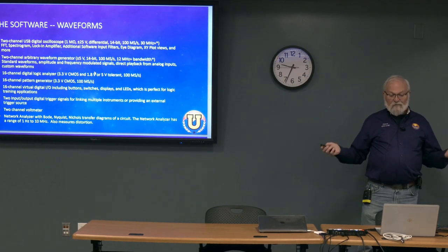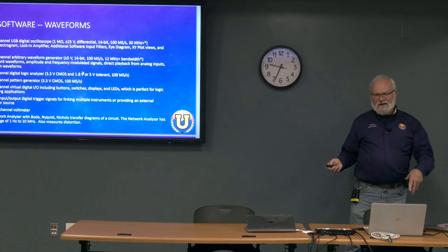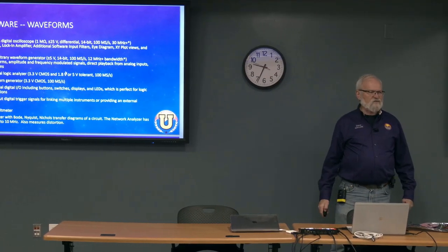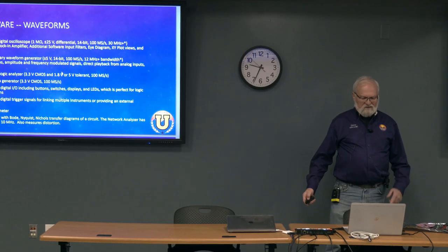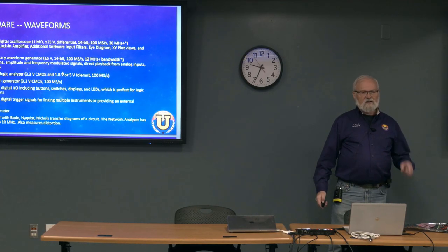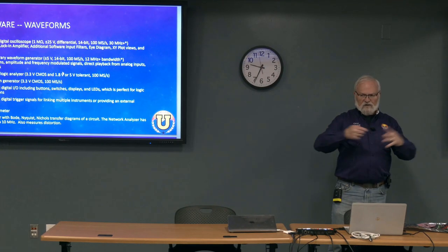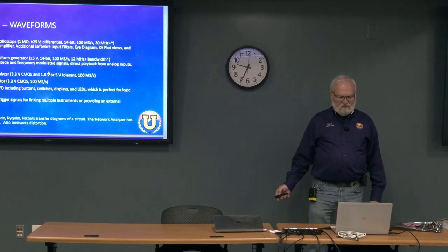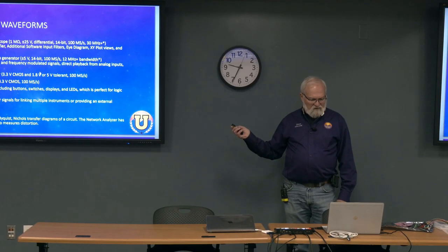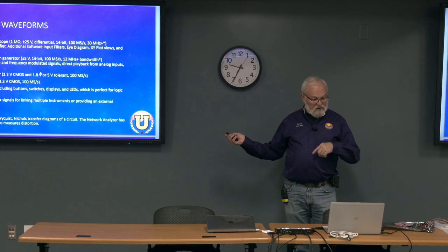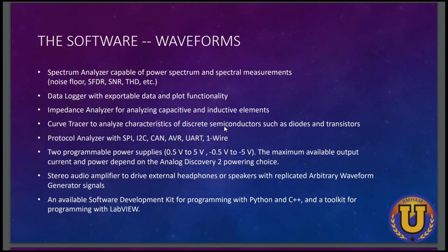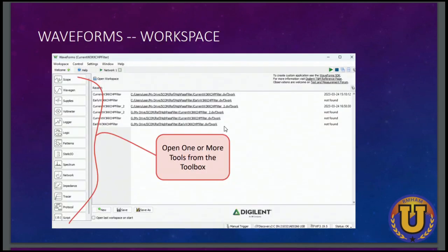And the waveform generator, it's not only sine waves, it's sine waves and square waves and triangles and sawtooth and just about all the ones you'd want. Oh, and it's got one called noise, and literally it's just randomized noise across whatever bandwidth you specify. It's got cross-channel triggering across things. The spectrum analyzer and network analyzer will also give you distortion.